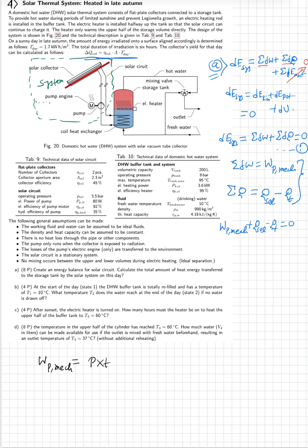They mentioned the pump power here, you can check, 80 watt. So I have to convert it to kilowatt. So it would be 0.08 kilowatt, and the time they mentioned is 6 hours. So if you calculate it, you will get 0.48 kilowatt hour.